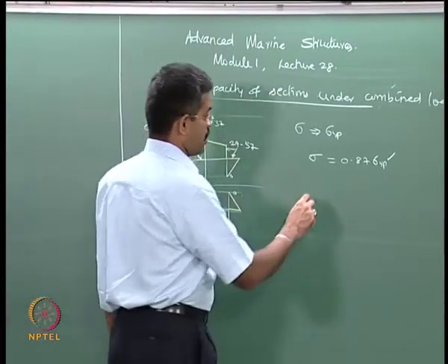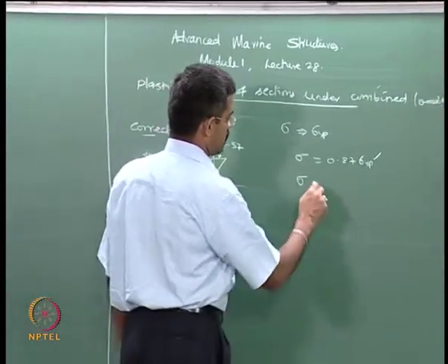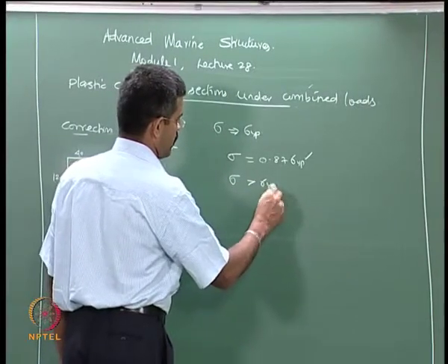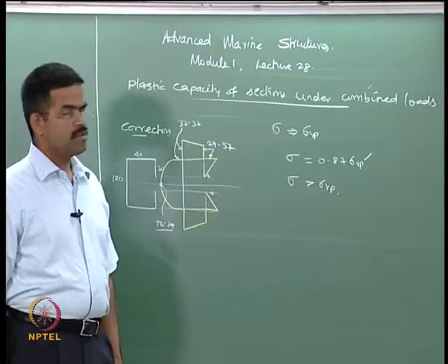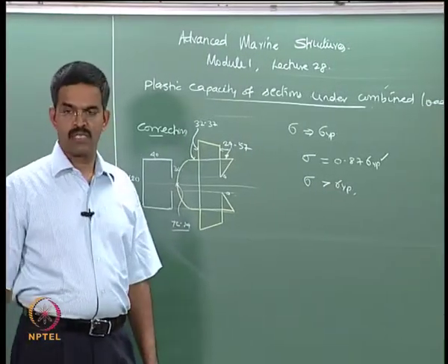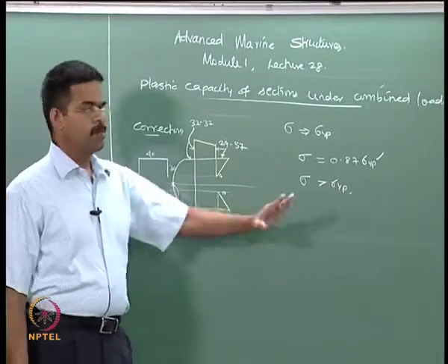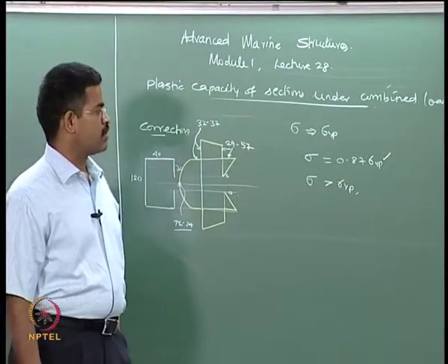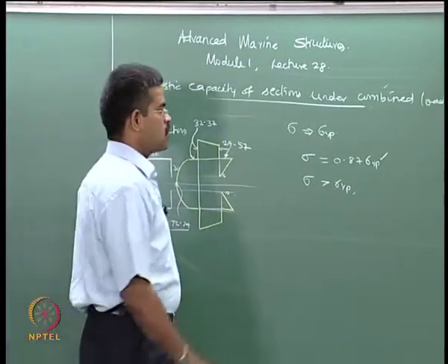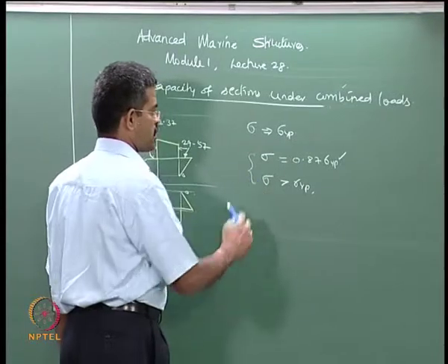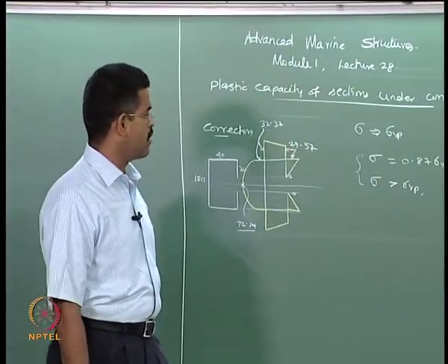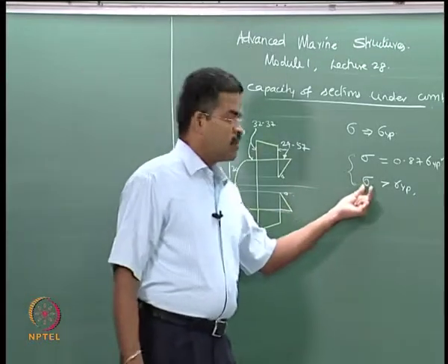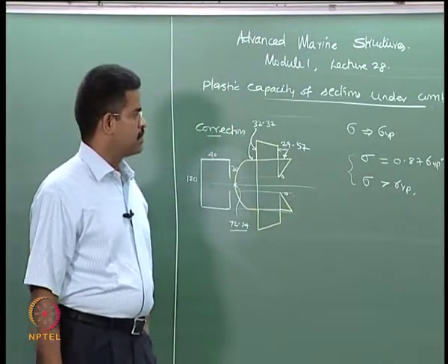The other theory says that if the principal stress exceeds sigma yp, there is a possibility that even then yielding will not start, depending upon the nature of the stresses and whichever theories we have used. So, those 5 theories we discussed in the last lectures help us understand the mechanism by which one can get the failure loads or the yield point stresses.